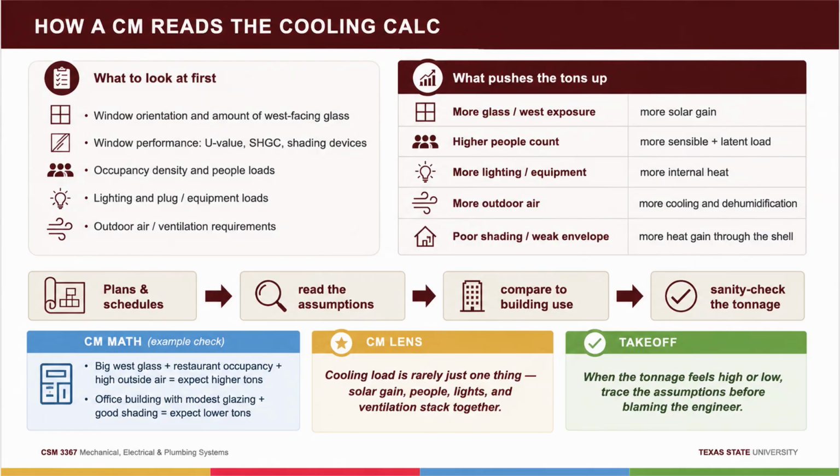3. Submittal review. When the mechanical sub proposes an in-or-equal unit, you now know the questions that matter beyond the tonnage on the nameplate. Does the sensible/latent split match the basis of design? Same story on a glazing substitution. If the SHGC moved, the load moved. You don't approve mechanical submittals alone. That's the engineer's stamp. But you're the one who spots that a substitution in Division 8 quietly rewrote the assumptions in Division 23. 4. Coordination and real estate.